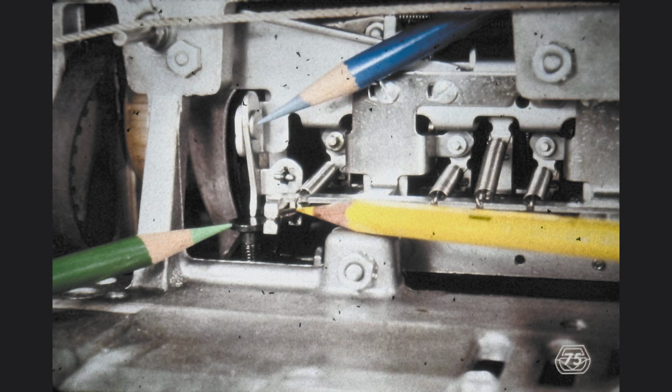The best angle for observing the R-5 rotate, or selector, latch is this one, from the rear of the machine. The blue pencil points at the pivot point of the -5 selector latch. This pivot point is fastened to the power frame of the machine. The green pencil points at the adjustment screw, which is fastened onto the -5 rotate bail. The yellow pencil points at the spring, which restores the latch after each selection. Notice also the restoring springs for the positive selector latches.